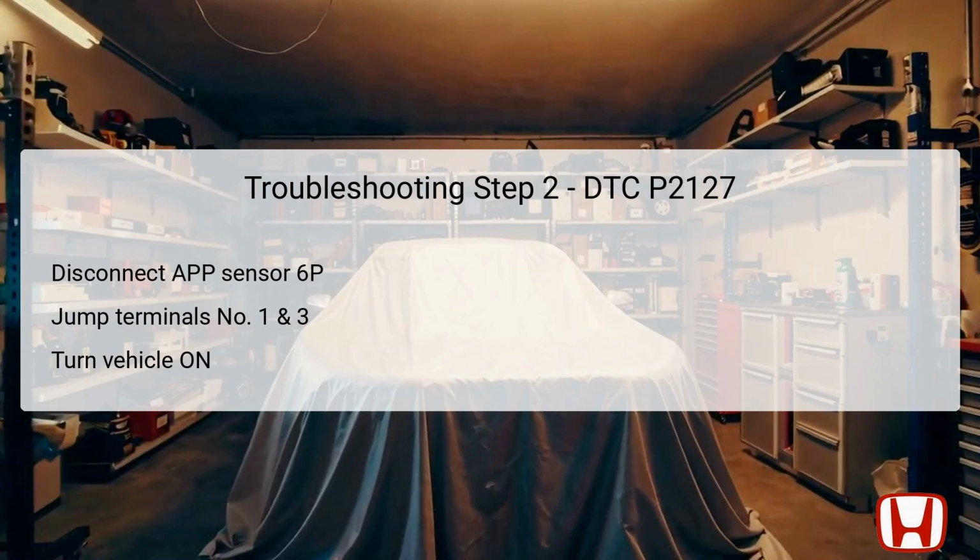The vehicle should then be turned to the on mode without starting the engine to observe the HDS tool's readings. The expected condition is that the voltage for APP sensor B should now read more than 0.2 volts. If it does, it indicates a fault is likely within the accelerator pedal module itself, rather than the APP sensor or its wiring.